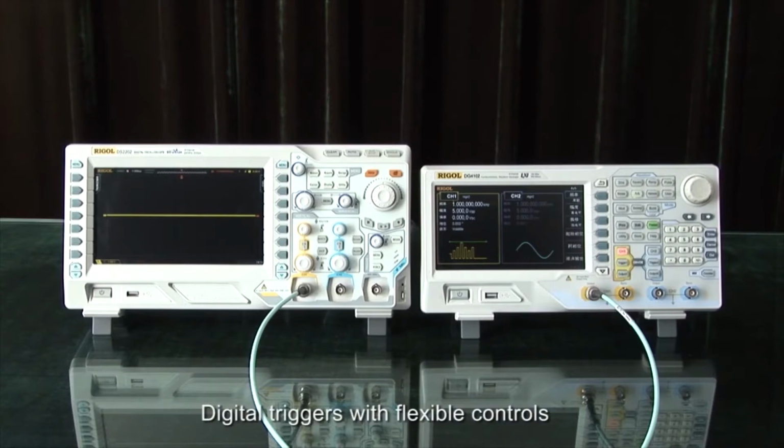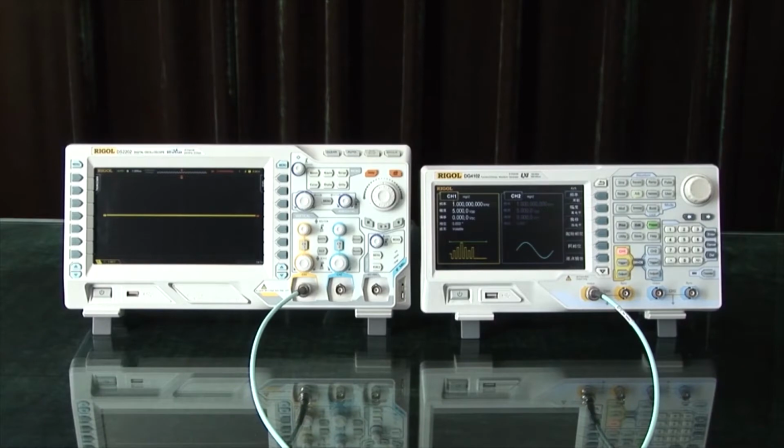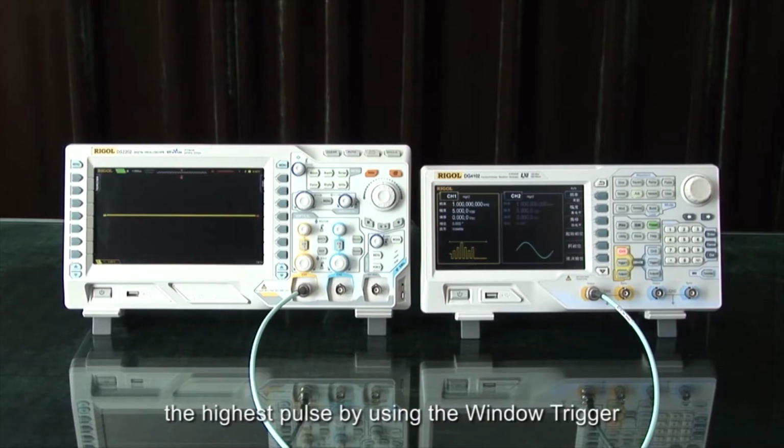Digital triggers with flexible controls can make troubleshooting problematic signals much easier. Here is a pulsed wavetrain with varying amplitudes. A traditional edge trigger will likely focus on the first rising edge of this wavetrain, but we can use the window trigger to focus in on a specific area very quickly. Let's have a look at how to trigger the highest pulse by using the window trigger.